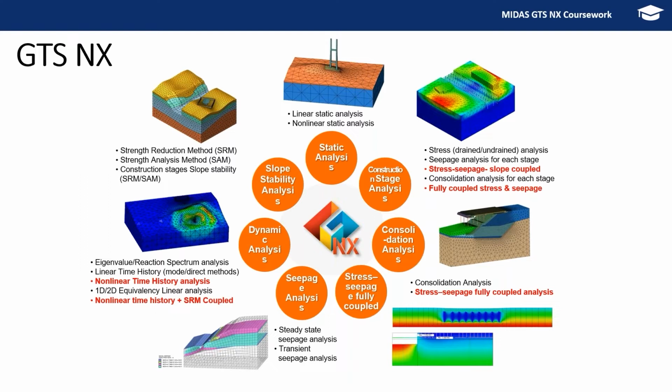Then you can go for construction stage analysis, where you simulate various stages of the construction. You can do stress analysis, seepage analysis, stress-seepage-slope coupled analysis, and also consolidation analysis for each construction stage. So we also have FEM methodology based consolidation analysis.